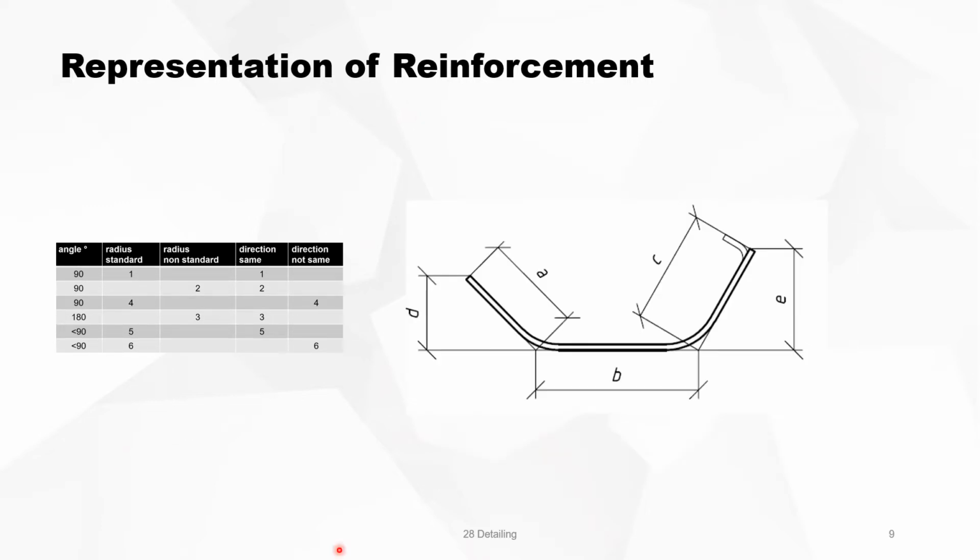Another example, we have here two bends. So the number starts with 2 and the two bends are in the same direction. So it's a 5. So the number is 25. You see that the hook, the little hook here, we do not count as a bend.